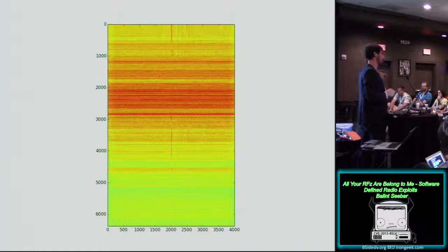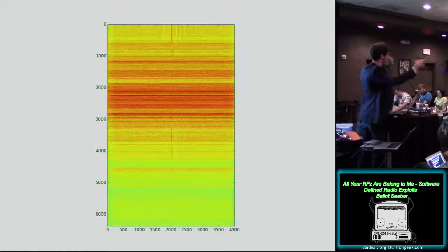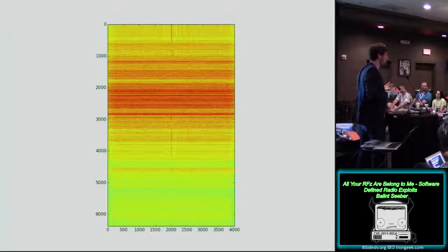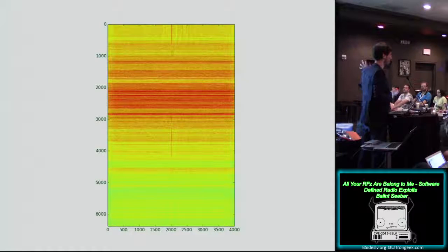But now considering that the car is moving, you could do other interesting things too, like maybe use this for passive radar. And people have actually done this with different television signals and even with FM radio, where you compare against your direct path of the transmitter, but you point your antenna out in the opposite direction, and then you correlate the two signals to see if you're getting any multipath reflections of things out there like aeroplanes. So it's actually a really cool way of detecting moving objects. And there's been some really interesting research done on this. Some people also used it to try to localize, I think, large ships using digital television signals.